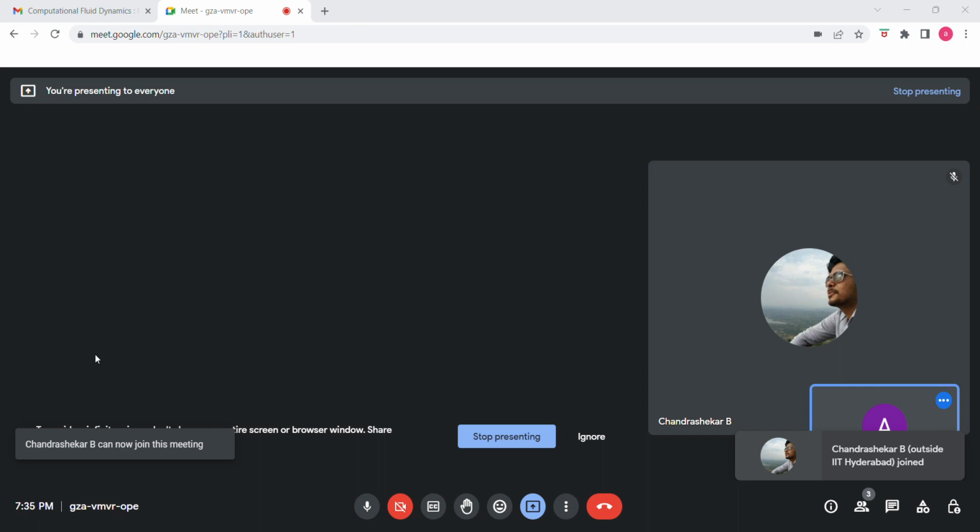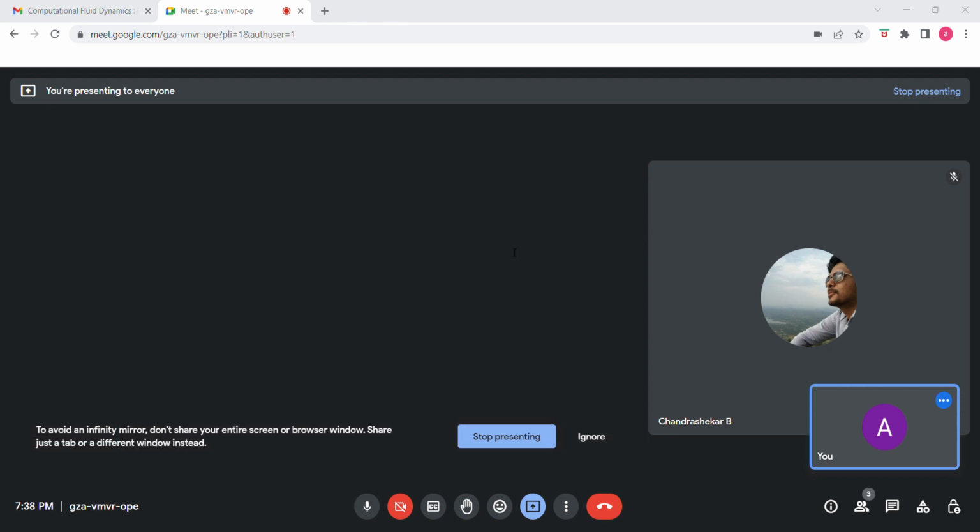In question 12, it is given that you wish to compute the steady laminar fully developed flow field through the triangular duct. For this case, which of the following is an admissible governing equation? It is given that del square w by del x square plus del square w by del y square is equal to 10, that is a constant. This is feasible.